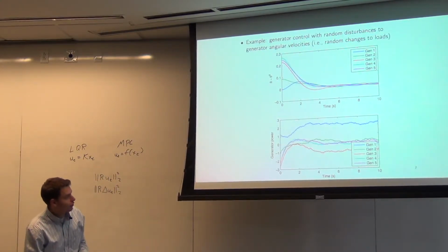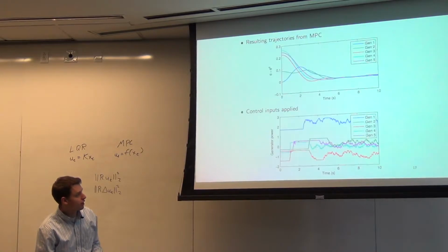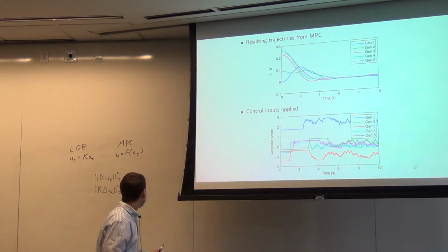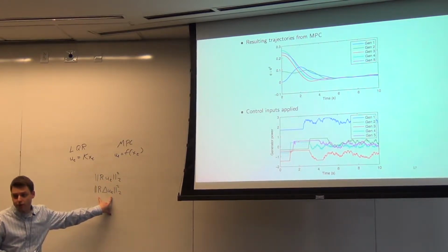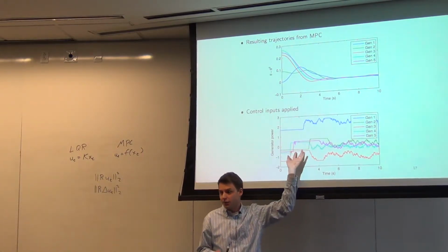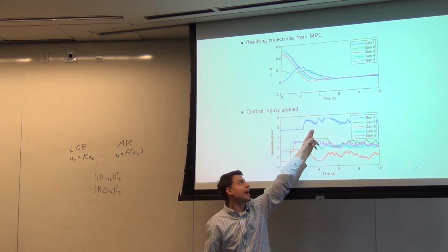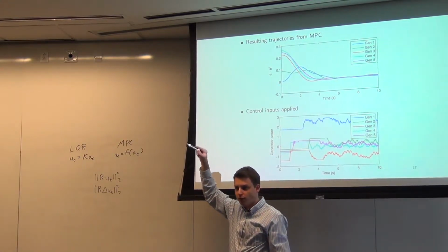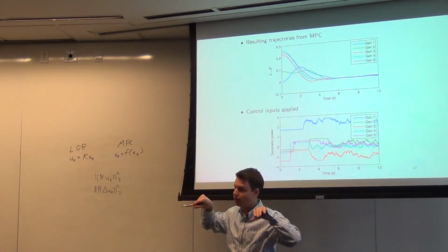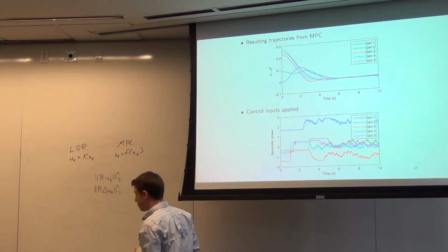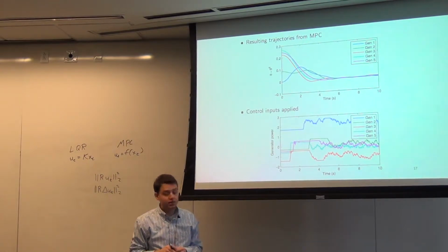So the same thing happened in LQR, and the same thing happens in MPC if we skip forward, right? So what you see here is, I think I just happened to pick one that was in between these two things. I'm using the exact same cost here, by the way. So I'm using the same cost functions we have for LQR. The only difference with MPC is that we do have bounds. So you see these things actually limited. Even when you're at the system state that you want to be in, you still may wander up a little bit, and you're still going to be clipped at that upper bound. So this is what the resulting trajectories and control look like for MPC.